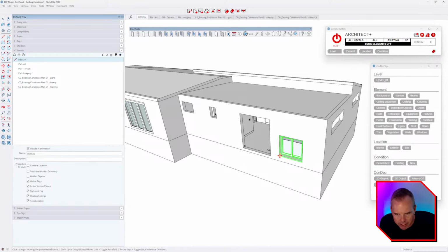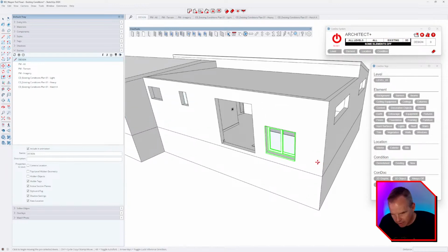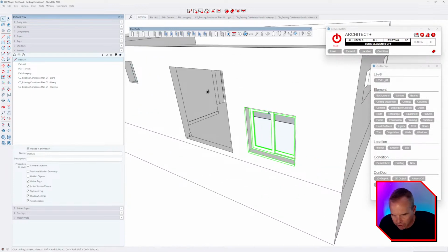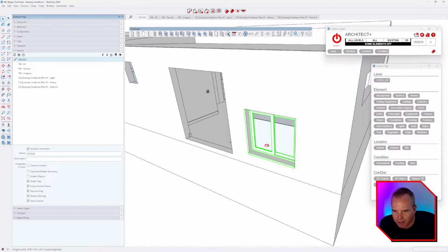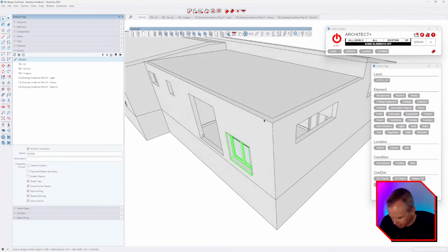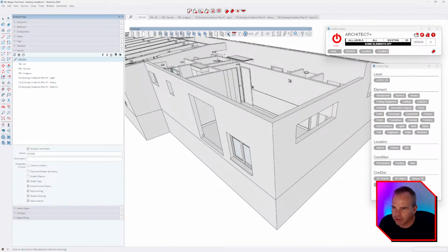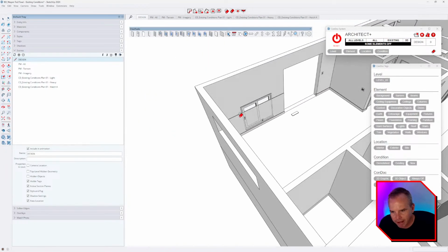I can just place it right here, and if I'm not mistaken, that's the wall cutter scenario happening, because see, this is a group that's been tagged walls. We tagged it interior and exterior and existing. And so this dynamic component is actually cutting through that group, all the way. Let me freeze the ceilings as well. And I'll update this just so that every time I hit reset, we're not getting back there.